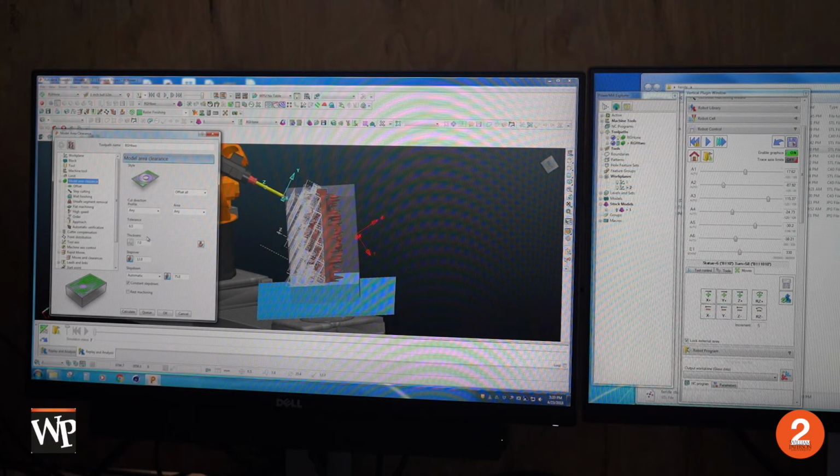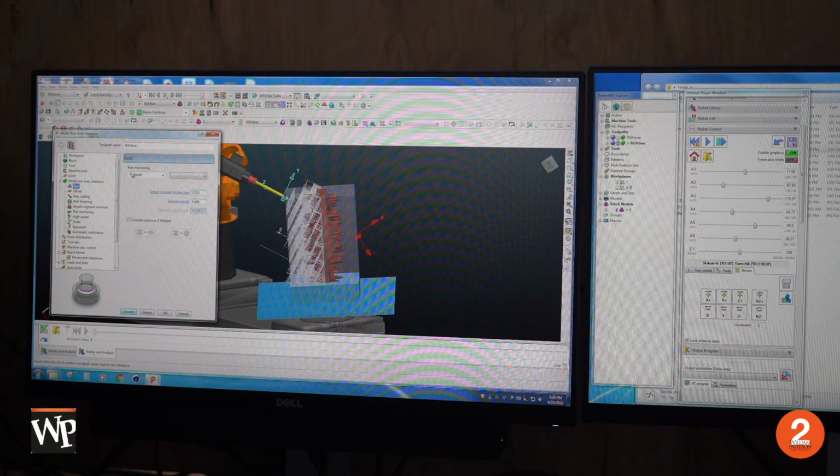Our settings for our tolerance, our thickness, our step over, our step down stay the same, and constant step down is always on. But we're going to click rest machining. Now this is where we're going to factor in the stock model we created. So now we have a setting called rest machining. We're going to use stock model 1 and the stock model state RGH1.